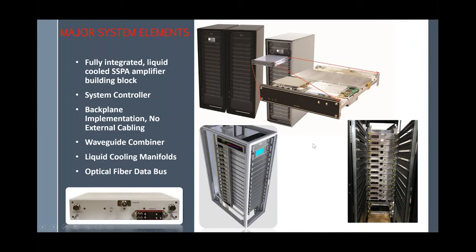And the backplane connections and mechanical interface design ensure dripless liquid cooling and hot swap capability for replacement of the individual 2U chassis. And I should say one thing about the combiner. The combiner is configured based on frequency and the number of 2U boosters. In this case, it would be a 16-to-1 combiner.